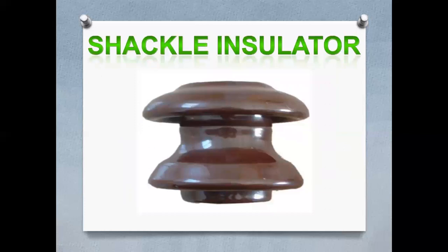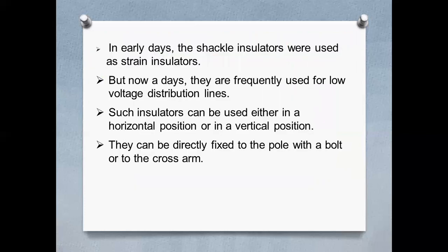Okay. And one more thing regarding shackle insulator: if the voltage is less than 11 kV, that is low voltage, we use shackle insulator as a strain insulator. For reducing tension, we use shackle insulator. So, you see, the same is mentioned here.